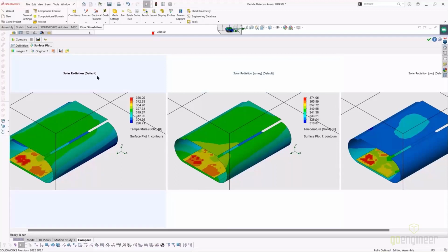But for the solar radiation on a 20% sunny or 20% cloudiness of the day, I wish they had better meteorological terms, but 20% of the sky is filled with clouds, presumably. Looks like we only got up to 350 Kelvin, so up to 50 Celsius, give or take. On a really hot day with no clouds, this was able to absorb some thermal energy and get above 50 Celsius.